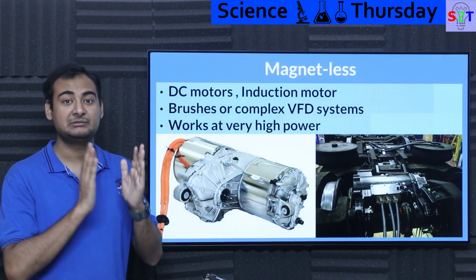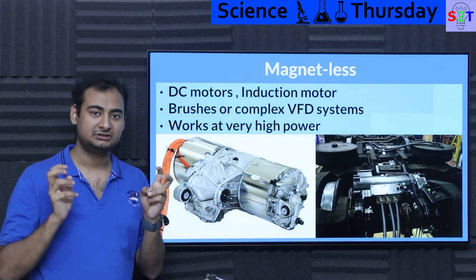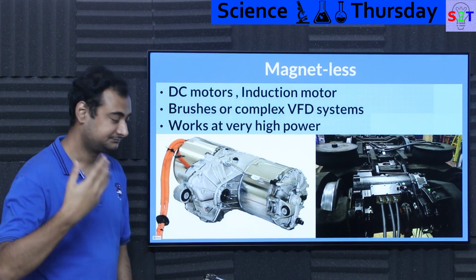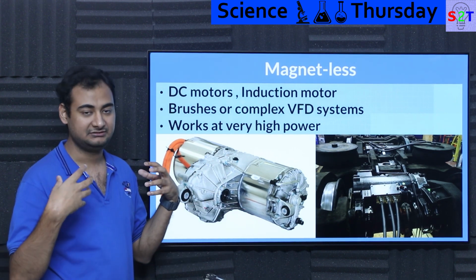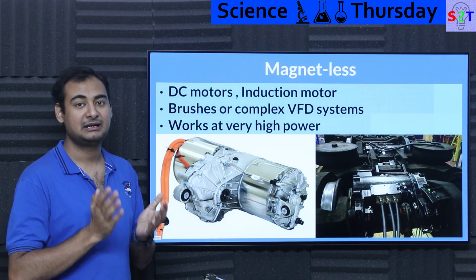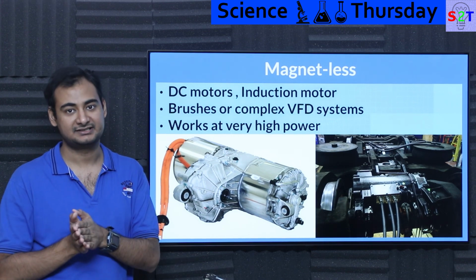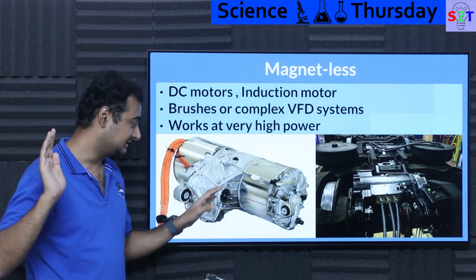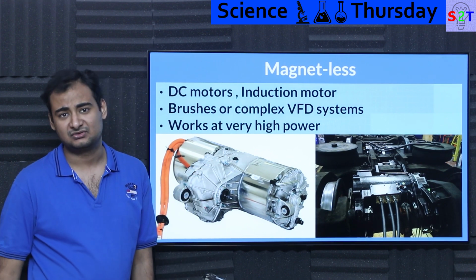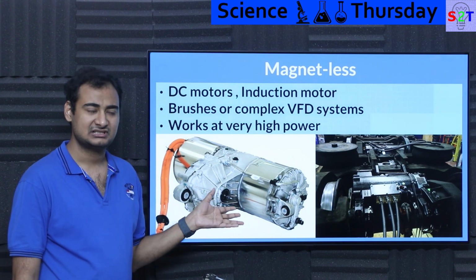Then how the heck will you make it into a regenerative system? VFD to the rescue, variable frequency drive. If you are familiar with what we call a grid tie inverter, think of it that way. Once you start to reduce the frequency, the rotor will think, hey, I'm spinning below synchronous speed. Basically I'm in positive slip. It will start dumping energy into the frequency, like how a grid tie system does. This way you can allow the RPM to go down very drastically. For the Tesla motor, the highest RPM is 20,000 RPM, and I'm pretty sure it will allow you to do energy recovery as low as 5,000 RPM.